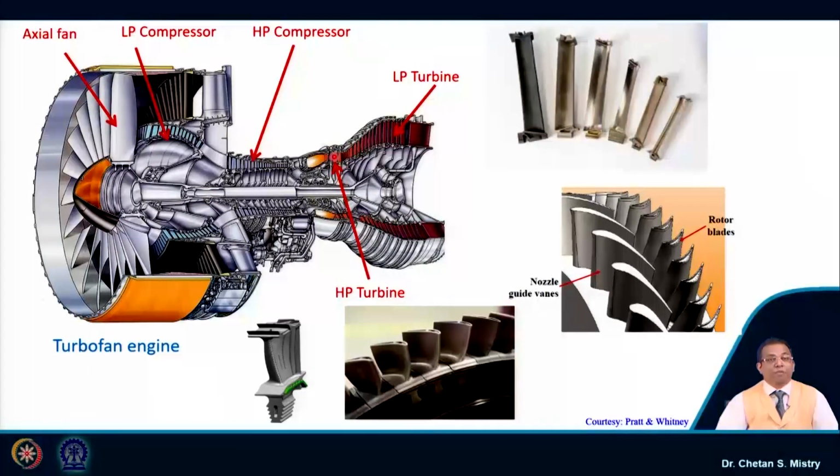The flow which is coming out from our combustion chamber has low velocity, maybe Mach in the range of 0.2, 0.3, and we want to accelerate our flow because we want to utilize the force that is coming from these high temperature gases. This particular device is what we define as the HP turbine. The flow coming out from the combustion chamber will be entering this device, that is what is called the nozzle.